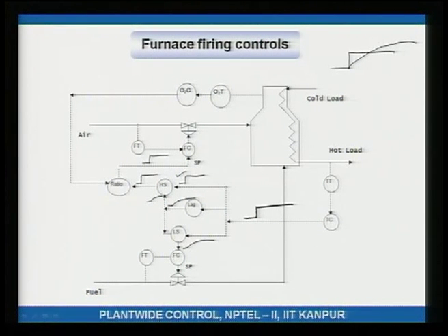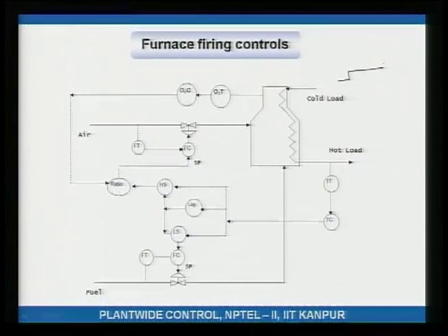Okay. Notice that these two need not be equal, because you will typically have, or maybe it will be like this, sorry. So, let us say the air to fuel ratio is, I do not know, 5:1. The air goes up like a step, the fuel will go up like an exponential. Okay. So, the fuel is always behind what? Behind the air. So, the air increases first and the fuel lags behind. Now, let us do the other part.